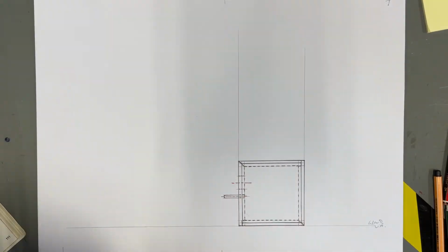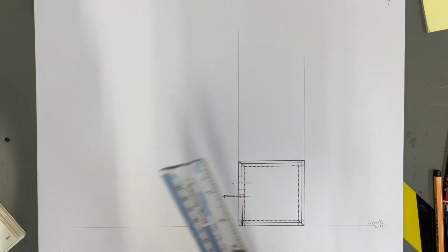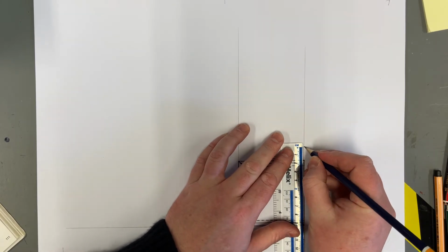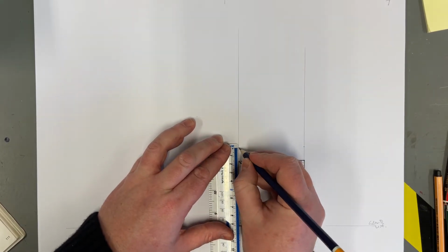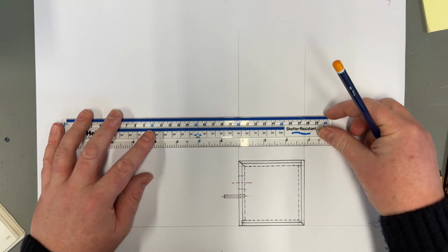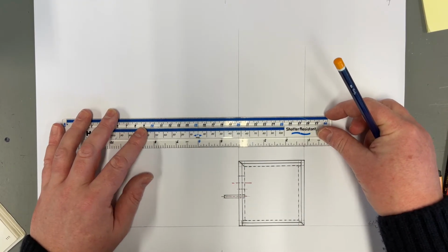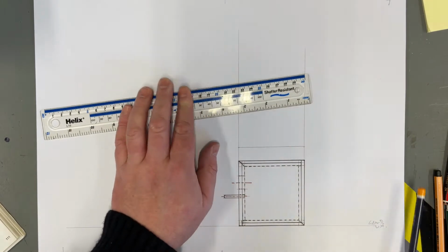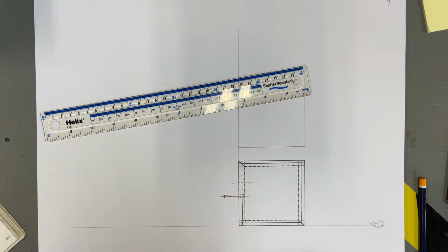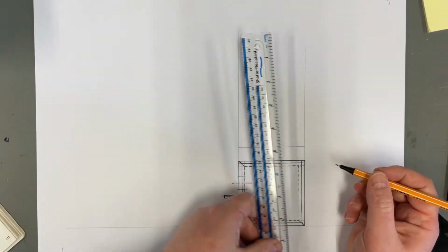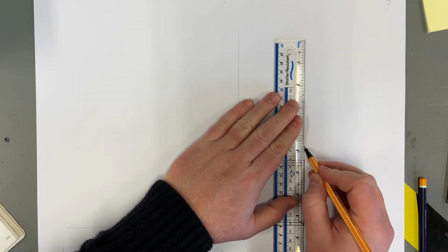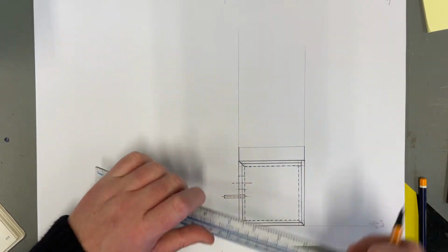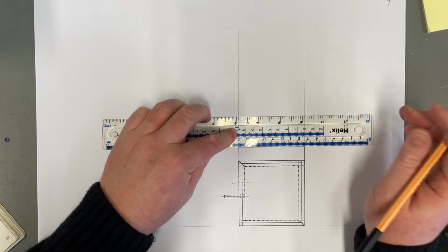Now the metal comes up, let's see. Yeah, that comes up about another 30 millimeters, so I will half that size and we'll go for 15. Same at the other side. Get my straight edge on again, and just make sure that it's still parallel to the ground line at the bottom. Construction line all the way across. And as we do see this, looking into that little gap, this would be a visible edge at the left and right, and also across the top, but we're not quite done there.